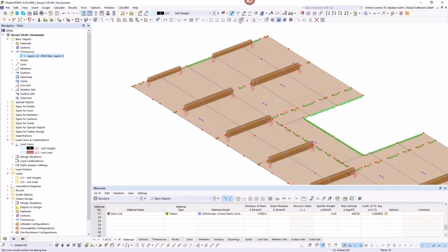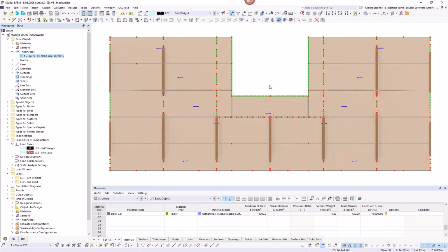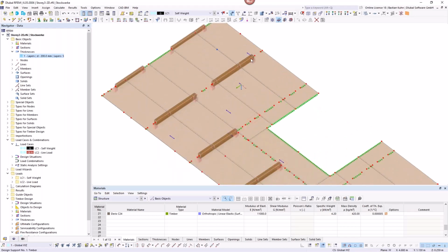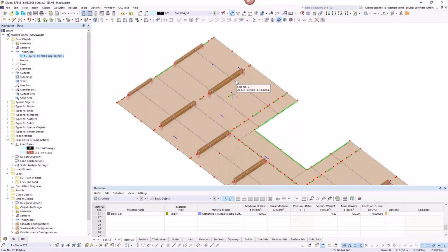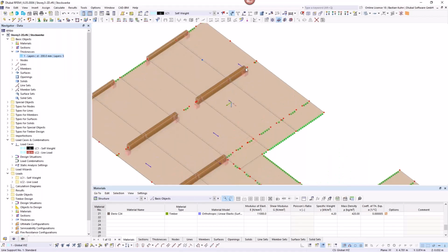There's nothing so fancy and new. But now when I'm working as a designer and constructing it, you probably realized already the blue arrows here. It was in previous versions always hard to know how I'm assigning the plates. If we look at the downstand beams that I have underneath those plates in here, you see that there's a downstand beam that is supporting this plate and this plate and this. Because of this connection point in here, it would not be possible to design it economically without this part. That would be quite hard. At least with screws, it can be a problem. And therefore, this beam was arranged in here. It's a continuous beam from this point to this point.